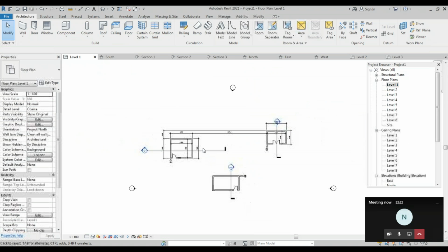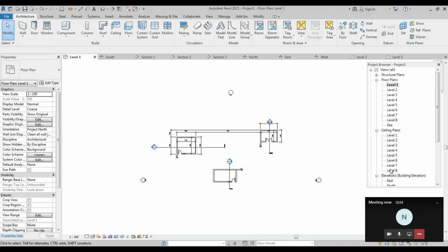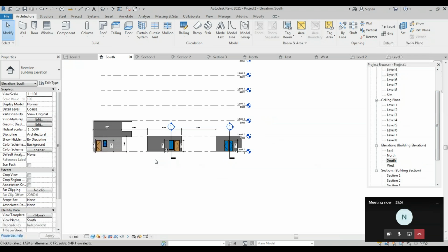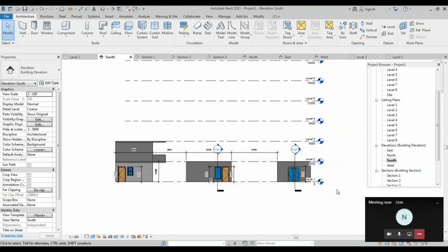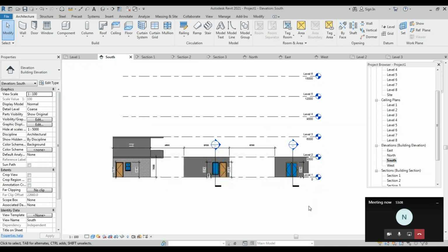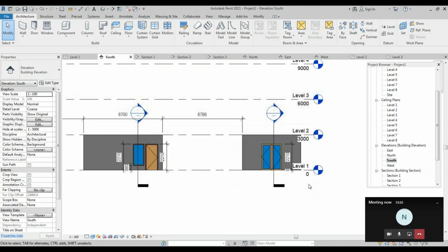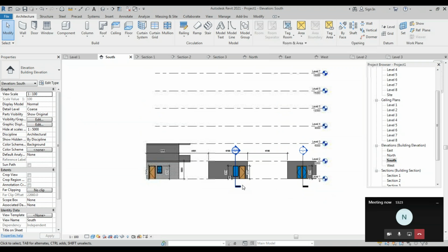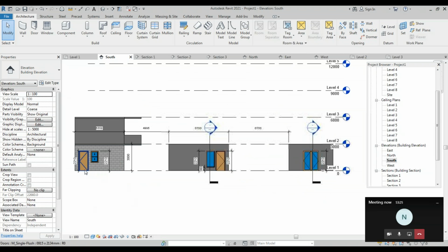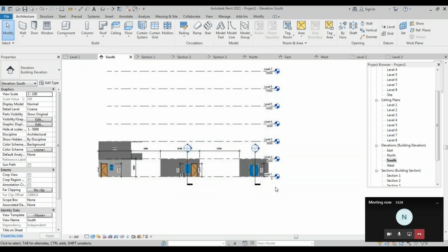Okay, yeah. So now the only thing which we left from the beginning is the plinth. We just forgot about the plinth, and we have done 2 floors, ground and first floor. Plinth is supposed to be coming below. So we cannot make the plinth below the ground level. Is it possible? No. It is always above the ground level, so that nothing floods and nothing enters. So that is the idea of having a plinth.